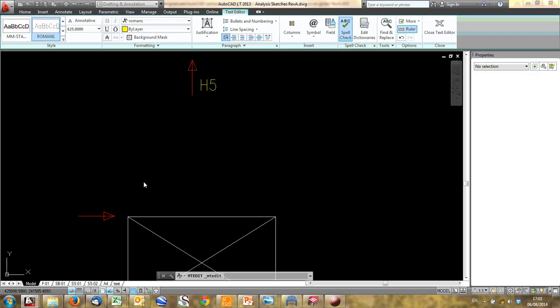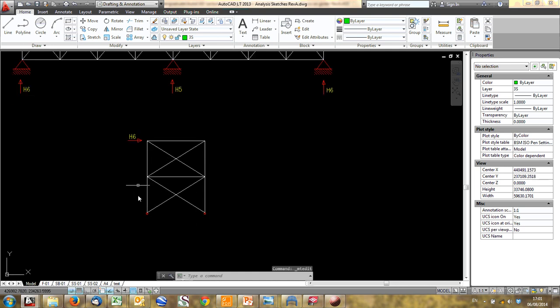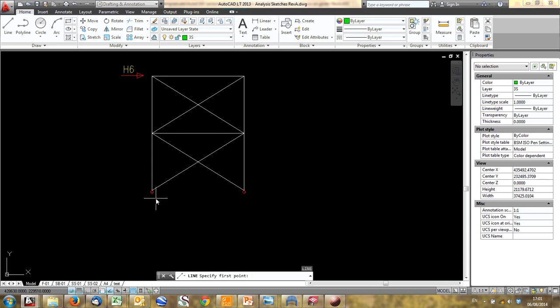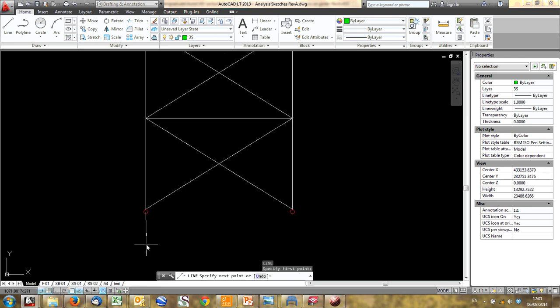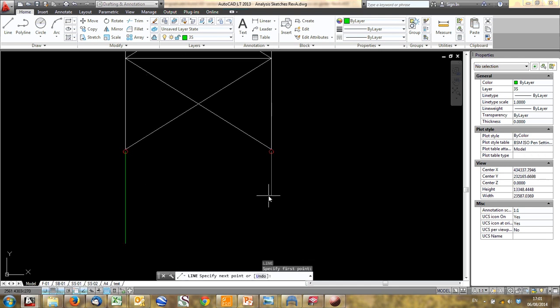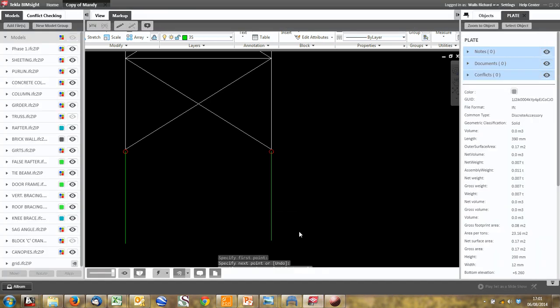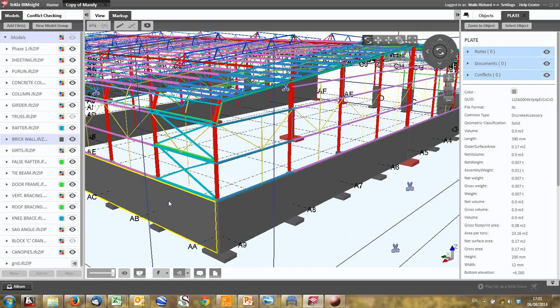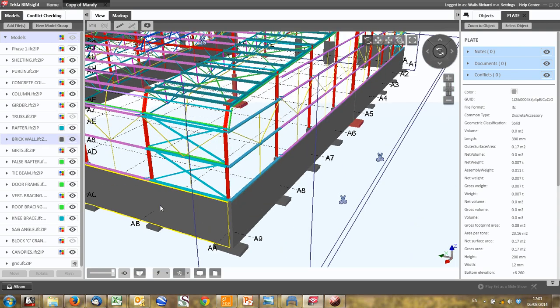And we've almost got our force all the way to the ground. I've just modeled the steel part at top and made sure these are pins here, but you could add the columns below as well. Why we haven't modeled these ones, or why we support them here, is that the brickwork is very stiff, and if you fix the brickwork to the concrete with hoop irons or whatever, this brickwork actually stabilizes your structure, so you don't necessarily need to brace below it unless you have very high loads.